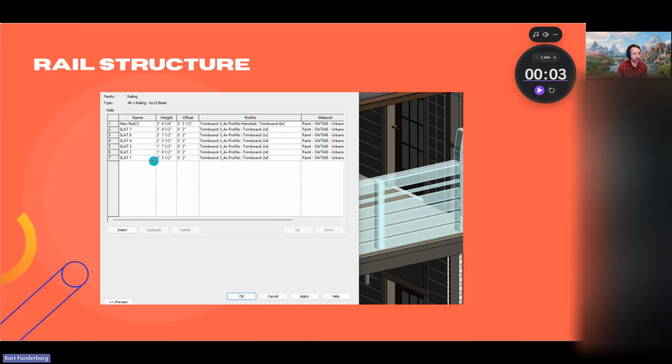But then I'm setting the height at 5.5 inches, which is the 1x6 trim that we're using, 2x6 trim, excuse me. And then I'm spacing that and counting 5.5 plus 5.5 plus the gap. So you're kind of seeing there's the 5.5 plus the 5.5, and then there's a gap number right there that's pushing it up. And this offset is interesting because that's allowing us to justify where it's sitting within the plane